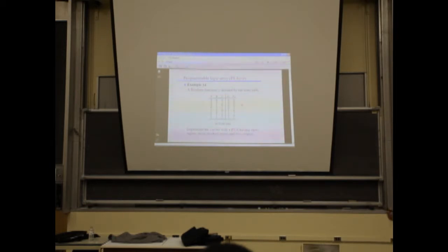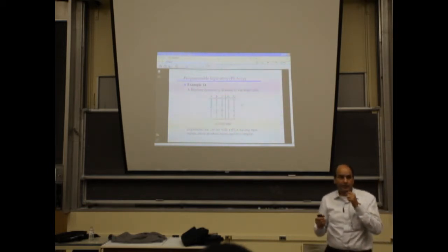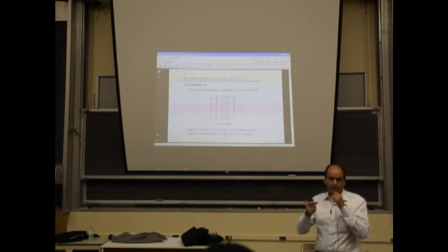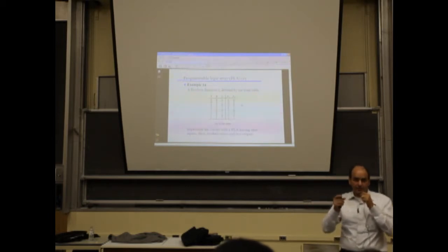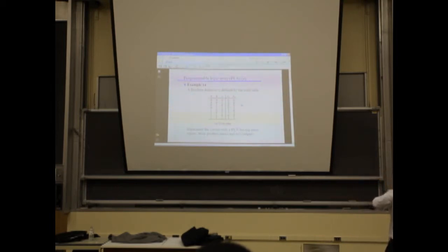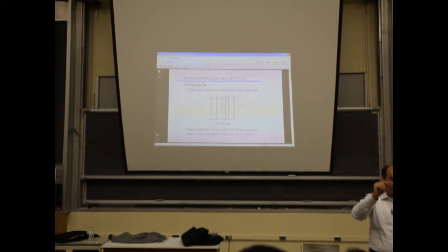So the question here is, how can we use PLAs and PALs to construct combinational circuits? So you know, one of them has a programmable AND plane and programmable OR plane, and we just have to fuse the right lines to synthesize a certain product term. The other one has only the AND plane to be programmable, and the ORs are already there for us. We cannot do anything about them. Is that right? You remember this?